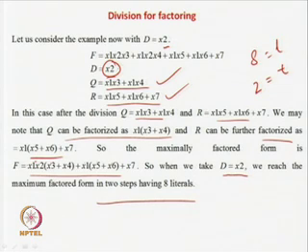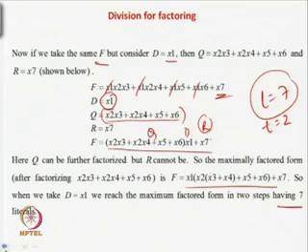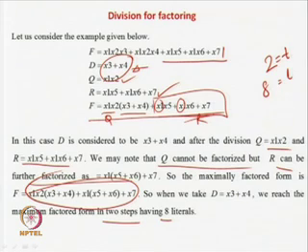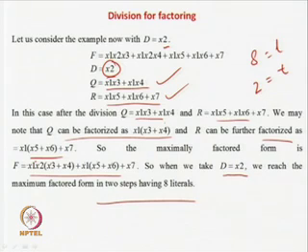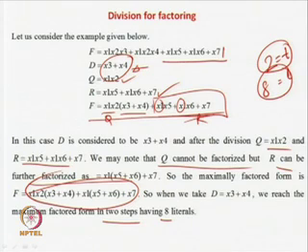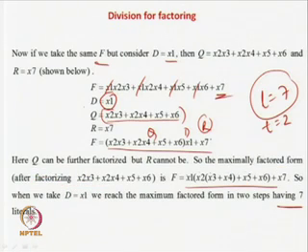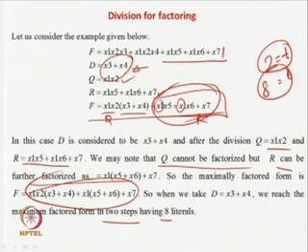So you can say that x2 is not a good divisor again, but it is a worse divisor than x3 plus x4, because with x3 plus x4 you require 2 time steps and the literal count is 8. In this case it is also the same, 8 literals and 2 time steps, but here after the first step you have to factorize both q and r again. If you take x3 plus x4, then time and literals are almost the same, but in the second step we are factoring only r, not q. So you can say that the best divisor among the 3 is x1, where we have 7 literals and 2 time steps, and you need to factorize only q. The second one is x3 plus x4, where the literal count is 8 and time is 2, but you are factoring only r.